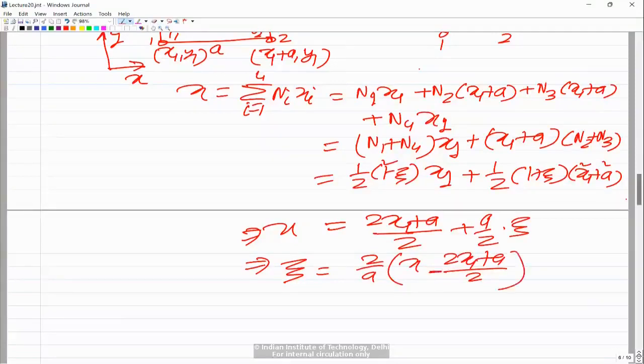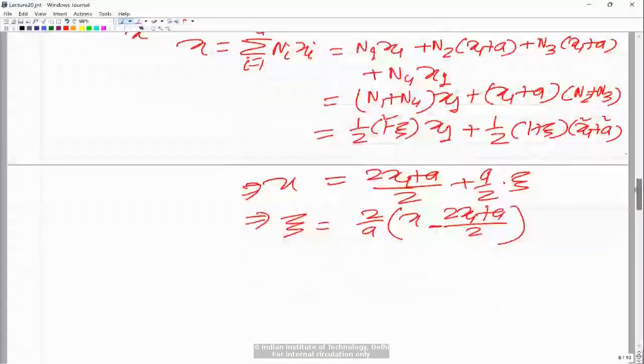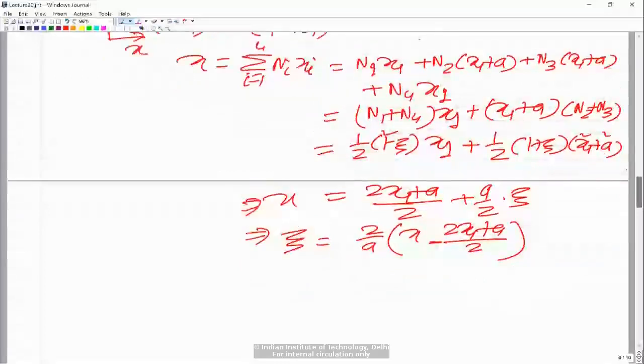So this will be the expression for xi. For arbitrary quadrilateral elements, this relationship is going to be complex. So usually we use the Newton-Raphson method to solve for xi and eta if we know a particular x and y, and the starting initial guess for xi and eta would usually be 0, 0.